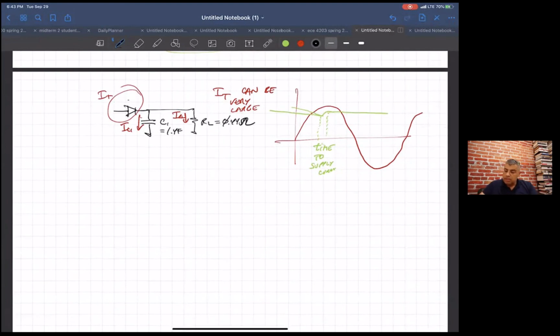So the current to charge up the IC1 is just C1 dV out dt. So that's C dV dt, right? And so it's kind of maximum right here when you turn on. This is the biggest dV dt. So that ends up being the point of maximum current. And I sub R, when you're on, stays the same as just Vp minus Vd on over R.